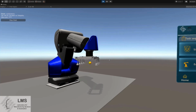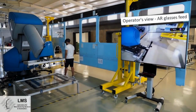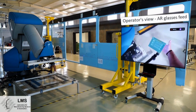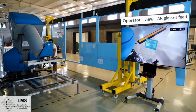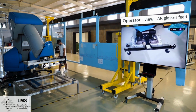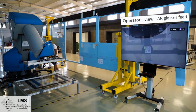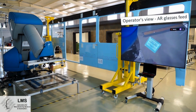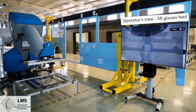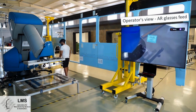This is the application we created, and now we can see how it works with the real robot. In live action, the first step the user must take is to calibrate the robot. As you can see on the screen, the user approaches the QR code placed on the back of the robot, presses the calibration button, and an X, Y, Z axis is created, allowing the entire robot to be calibrated. You can now see the hologram on the real robot.